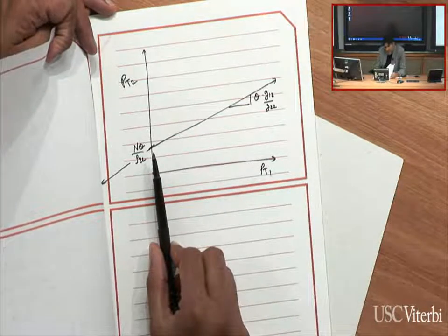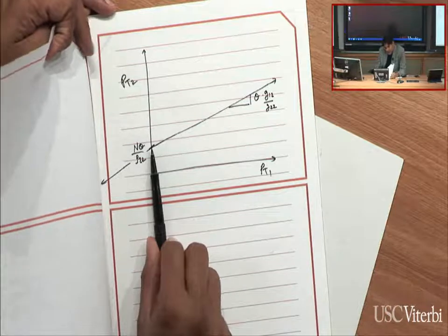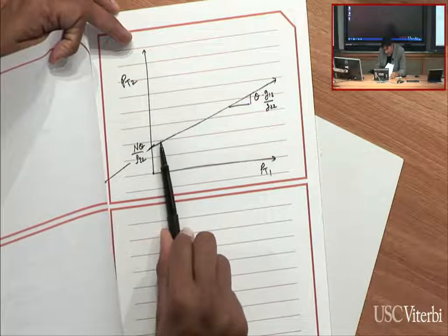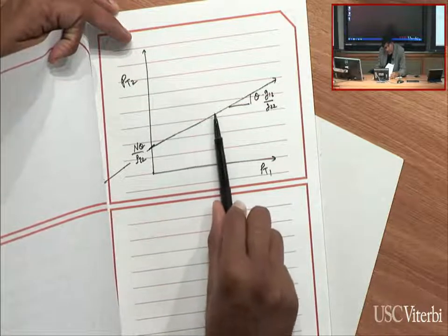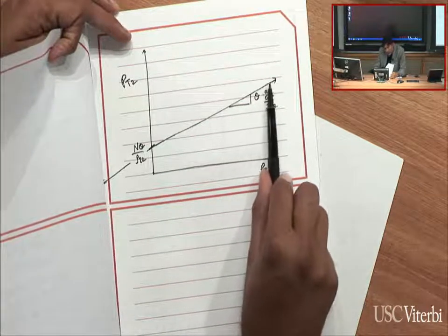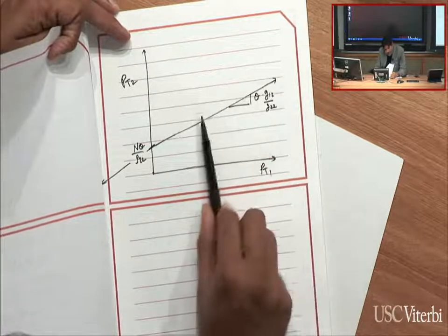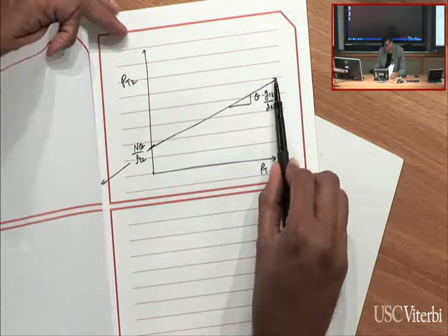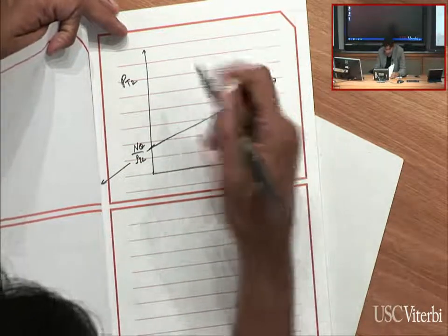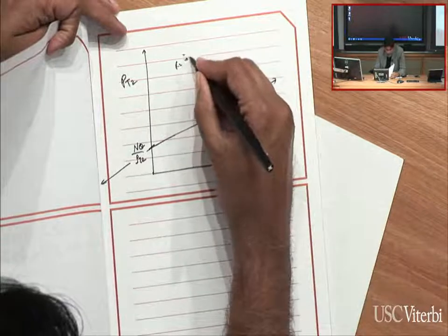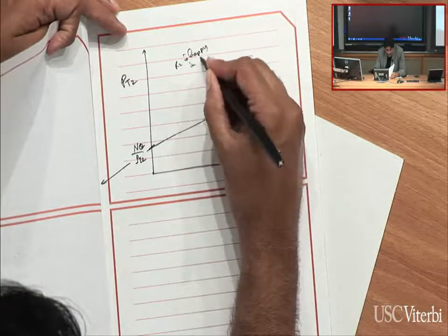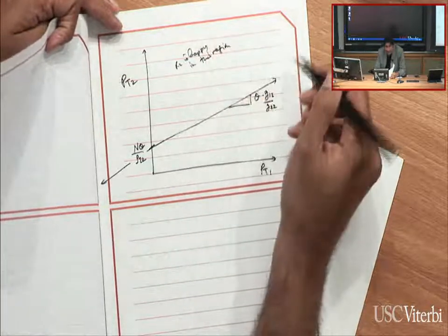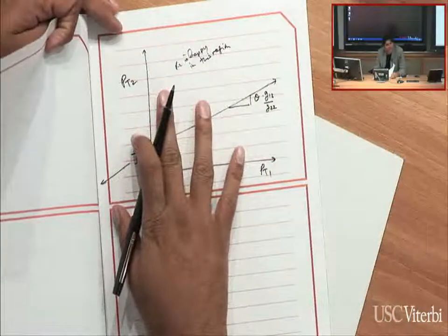So what this is saying is, if there's no other interferer, I need to make sure my power for this link is above this point. As the other node starts to transmit to its receiver, it's causing interference, and to deal with its interference, I'm going to have to boost my power level higher and higher and higher. The minimum value it can take on gets higher and higher and higher. Right? Everything above this, receiver 2 is happy. Okay? So in this entire region over here, receiver 2 benefits.